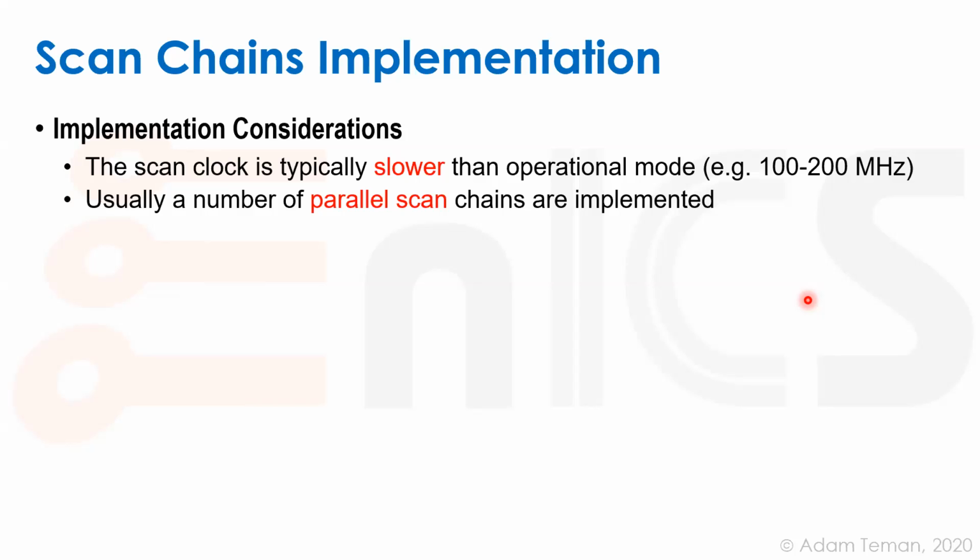Okay, so as Udi was starting to say, we don't usually use one big scan chain that connects all of the flip-flops in the design. What used to be done was we would take all of our IO pins that we didn't need, almost all of our input and output pins, and in scan mode, use them. Each pair could be one scan in and one scan out. If we have 100 pins, we can make 50 different scan chains. If we have 50,000 flip-flops, we can have chains that are only 1,000 flops long and not 50,000 flops long.